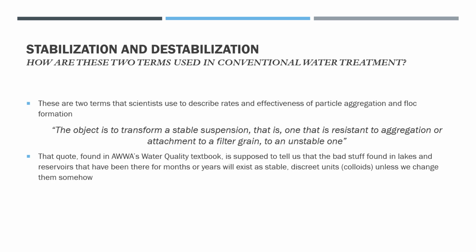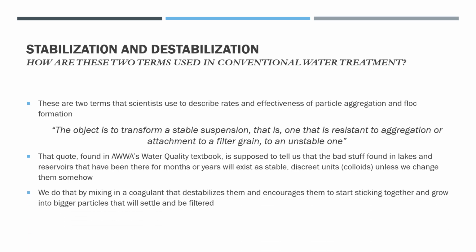Now that quote, which you found in the AWWA water quality textbook, is supposed to tell us operators that the bad stuff that we find in lakes and reservoirs has been there for a long time. It exists in a colloidal state, which are stable and discrete units that tend to stay in suspension and won't settle out on their own unless we do something about it. It's a very stable suspension of particles. So we're going to try to destabilize that. We're going to do that by mixing in a coagulant. The coagulant will destabilize the aggregation, encourage these particles to start to stick together, and in doing so they grow bigger. They're going to be able to be settled more efficiently and filtered.